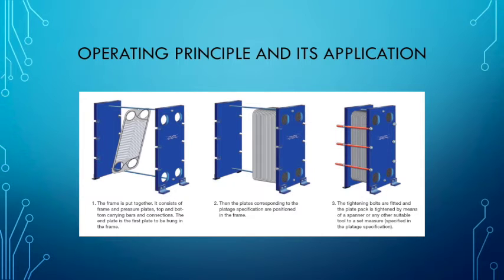Okay, how it works. The gasket plate heat exchangers optimizes heat transfer. The corrugated plates provide easy heat transfer from one gas or liquid to the other. Plates from a gasket plate heat exchanger are with elastomeric gaskets. These seal channels and direct the mediums into alternate channels. The plate pad is between the frame plate and a pressure plate. It is then compressed with bolts between the plates like this.